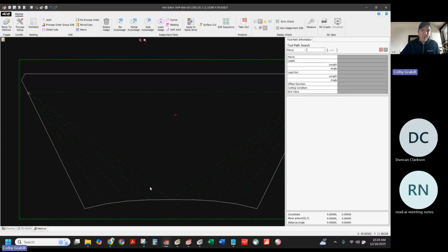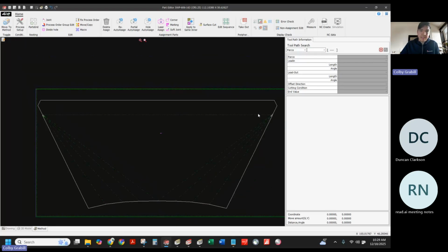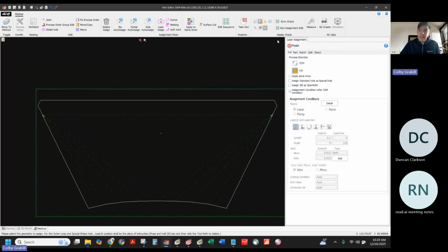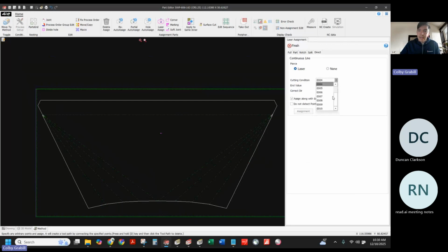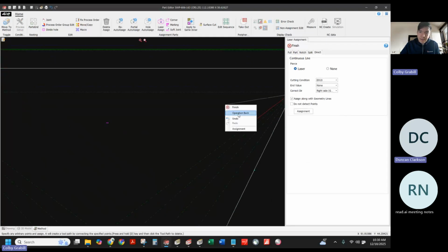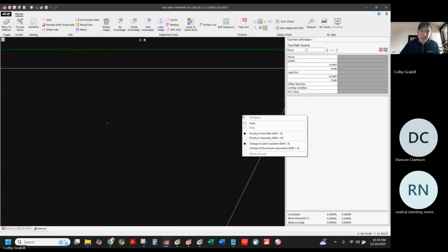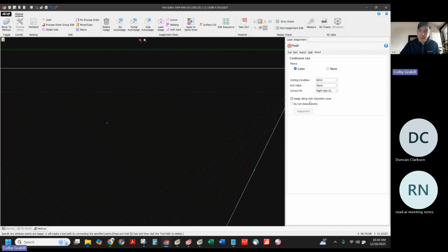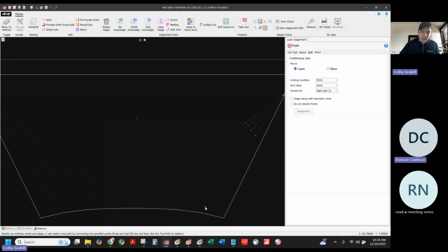And then for my bend line references, obviously you don't want to etch the whole bend line because that would take a lot of unnecessary time. Yep. But I can go into my laser assign, direct assignment, and E10, and I can just go in and arbitrarily, let me, I didn't hit complete, but you get the idea here. So now that places, these are just arbitrarily placed, but it's accomplishing that goal.